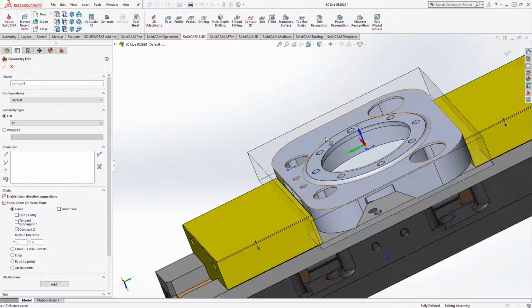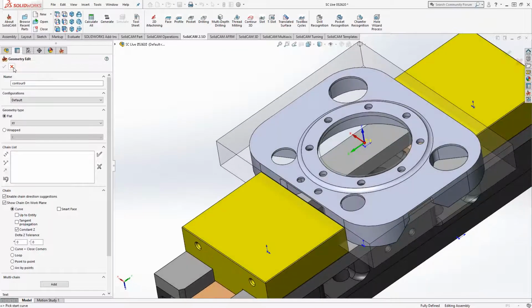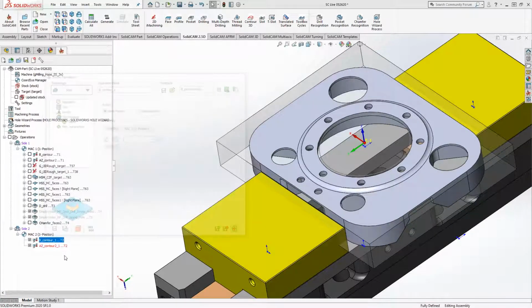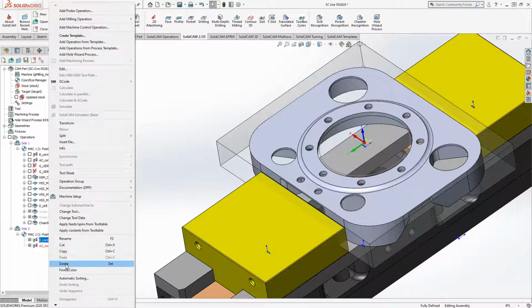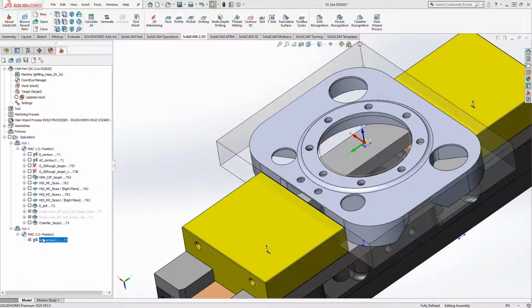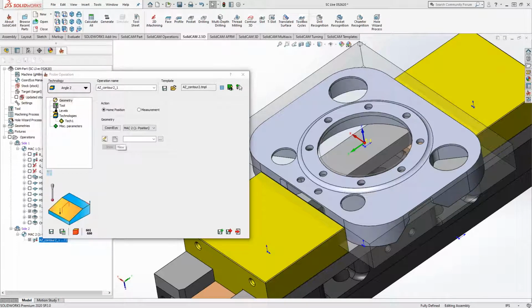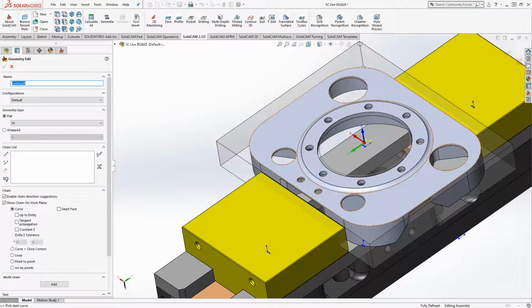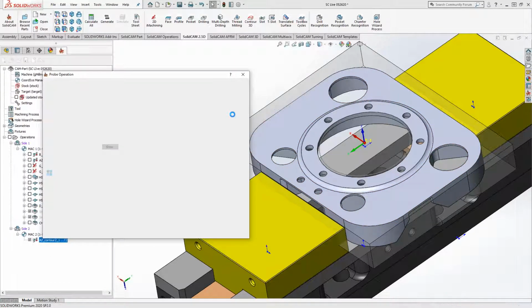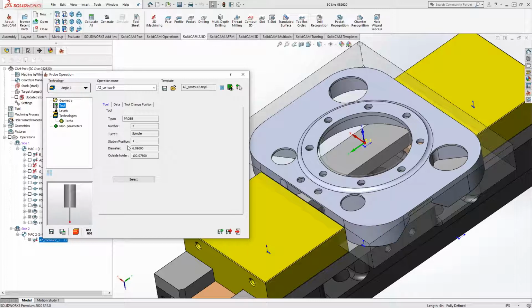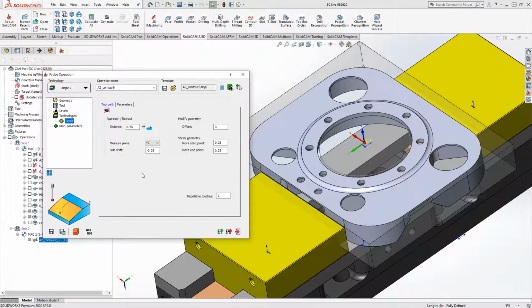Okay. Or like Scott just wrote in there, you could probe up that bore too. We could, but then we're not using the template, but we could. So let's get rid of this guy then. So first we can establish our Z since we already have this here. And that'll just be its line right here. So from the template, all of this is the same. We're just going to go to our Tech 1 and make sure that all of this makes sense.